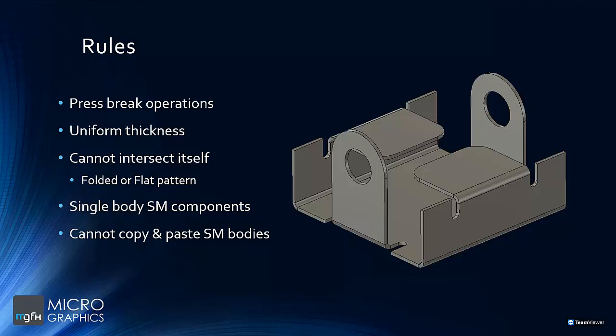The material has to be of a uniform thickness, with no areas thicker or thinner than the specified sheet metal thickness. So bearing in mind, the components are made from that flat sheet stock, so we need to stick to that thickness.